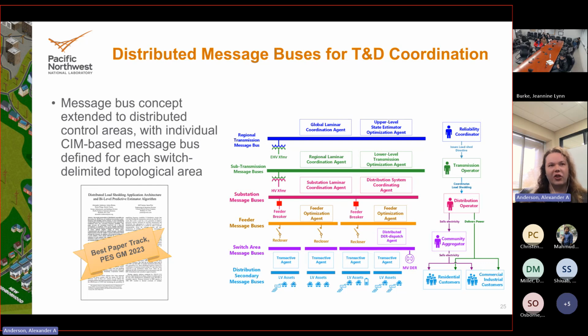Does the substation controller really care about the individual messages between different components within the microgrid? No, it just cares about the total P and Q and what impact it's having on the overall transmission system and equipment within the substation. So by doing that data compartmentalization, you make the problem significantly easier.